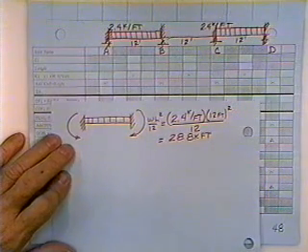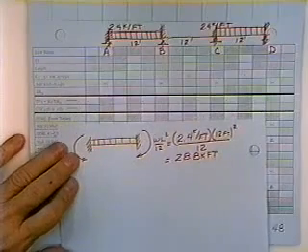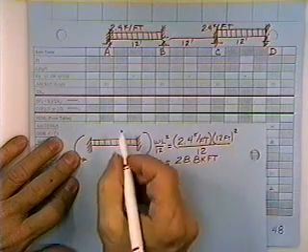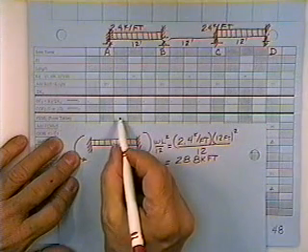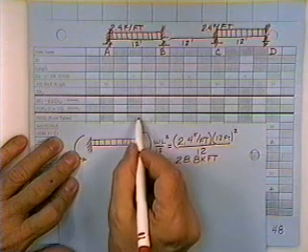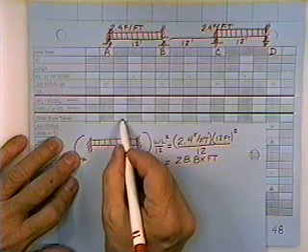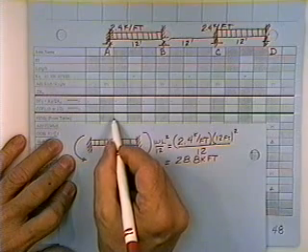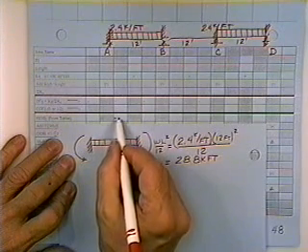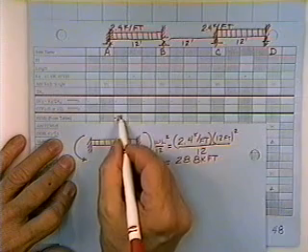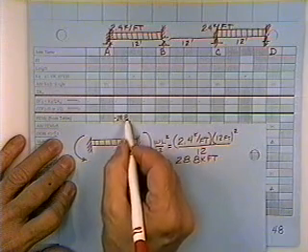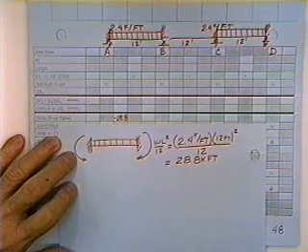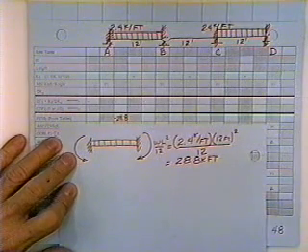So what I'm going to do is, if you'll look in your table, you will find a thing called fixed end moments. Beam AB has a couple of blank spots in the table to enter the fixed end moments on each end of the beam. Next to A, I'm going to list minus 28.8. That's how much moment a guy with a wrench would have to produce in order to fix the left end of that beam, which shouldn't be fixed at all.